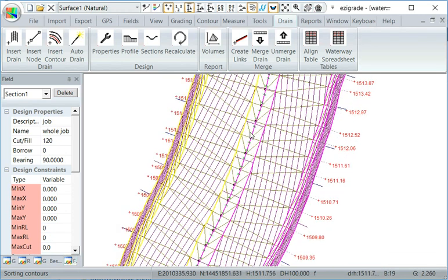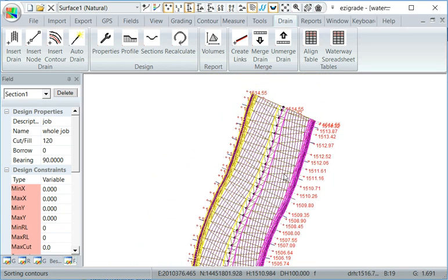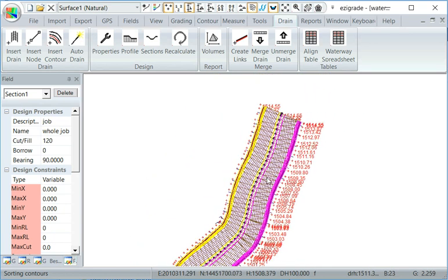So if you look here, that's the center of the drain. It's flat, goes out 12 feet, then it rises up to 72 feet out. Then from 72 to 76 feet, it's flat. Then it drops a little bit to 80. Then we're battering off back to the natural surface there. So that's basically our design.